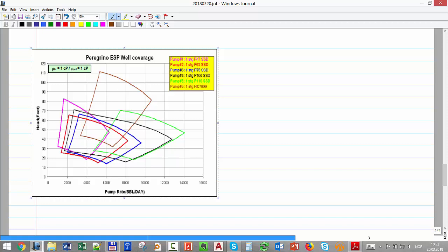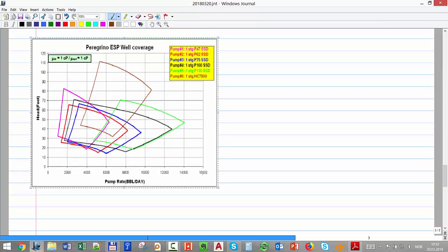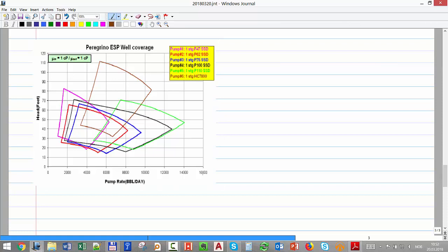Okay, now, we have one last thing before we go to our exercise today. Are these pump curves based on reservoir conditions or surface conditions? These are for, remember, the rate shown here is always for local conditions. If you want to see if your pump works or not, you have to use the rate at local suction conditions, at the suction of the bottom hole pump.